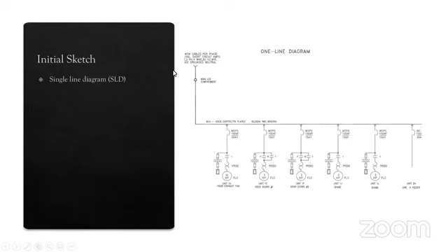that will be a single line diagram of the plant or the control panel, whatever it is. So the single line diagram will consist of basic components. That will be your main incomer, and then all the points will be shown as only a single line. If we have a three-phase supply, then the three phases will not be shown with three lines. It will be only a single line. So that is the single line diagram. And the single line diagram will also consist of all the loads that we are going to control.